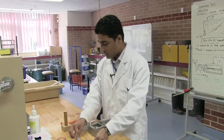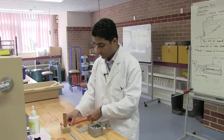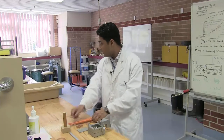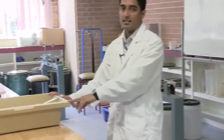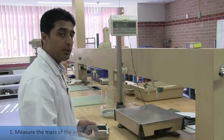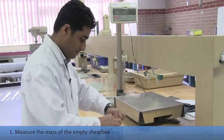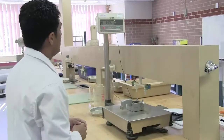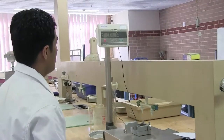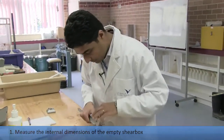The equipment to conduct the shear box test is the shear box itself, a vernier caliper to measure the dimensions of the shear box, a metal scraper, a tamper, a hammer, the shear box testing apparatus, and obviously the sand sample. First, measure the weight of the shear box with the cap in it. So place it inside and measure the weight. That's 3.308 kilograms.